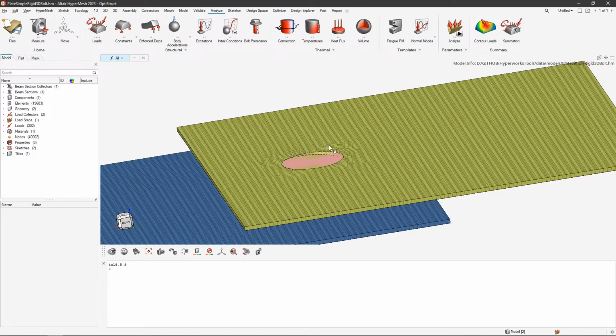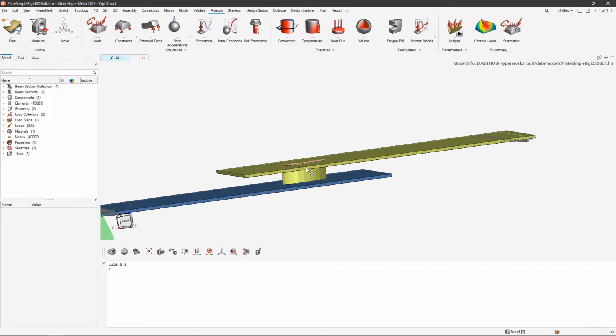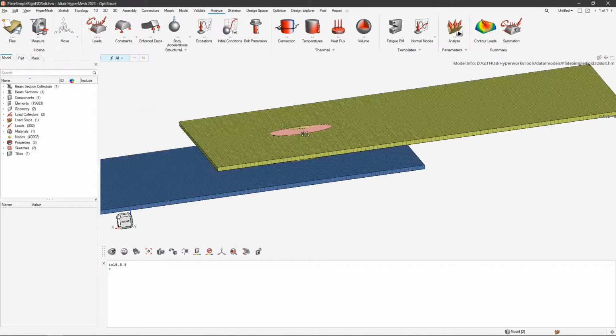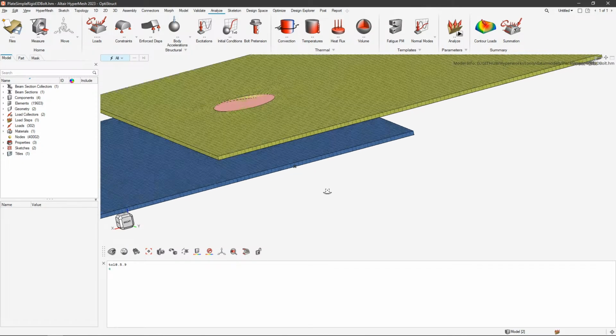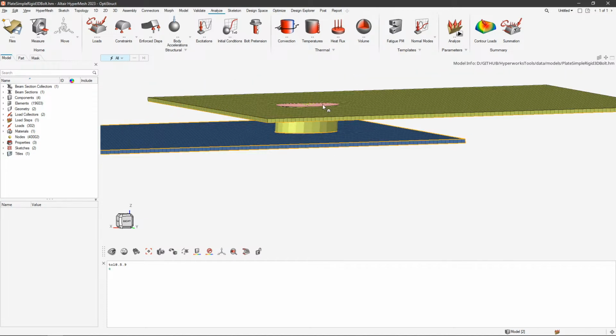And let's linger a little bit around why I think it makes sense to spend a little time thinking about something like this. So if you have something modeled here between those RBE connections, this would be from the detail stage of modeling. This would be one stage above the initial one where we just have an RBE element connecting the two parts, right? Connecting the two parts with an RBE2 is just infinite stiffness between those two parts. So it's not really realistic, it's just a quick way to get a connection there.